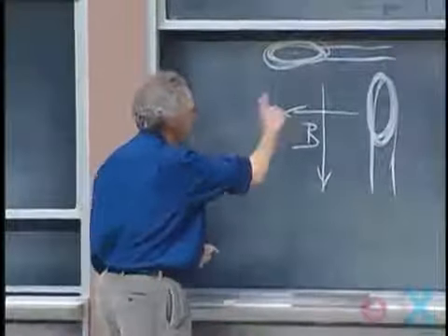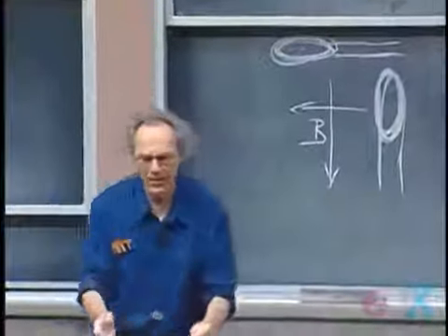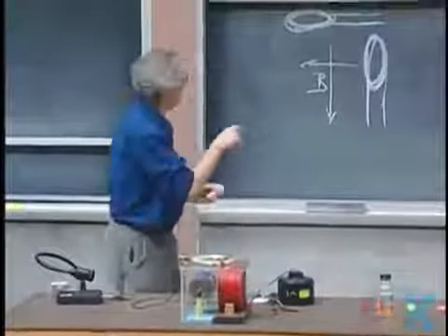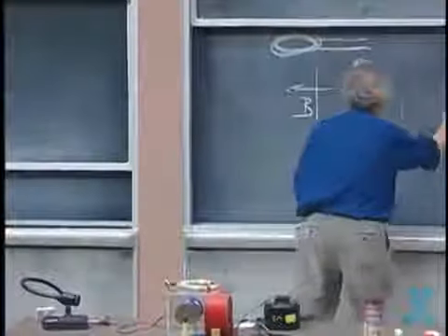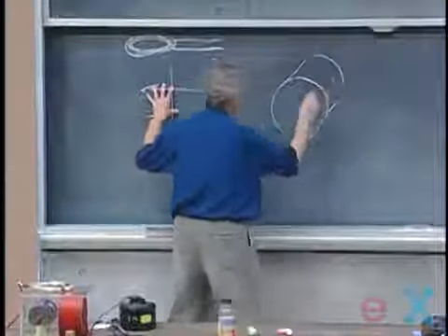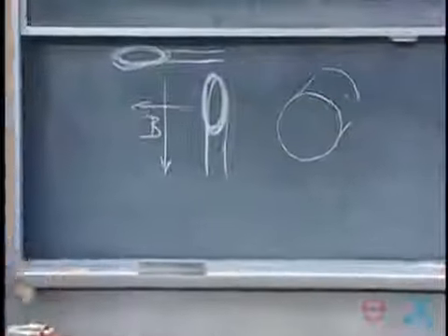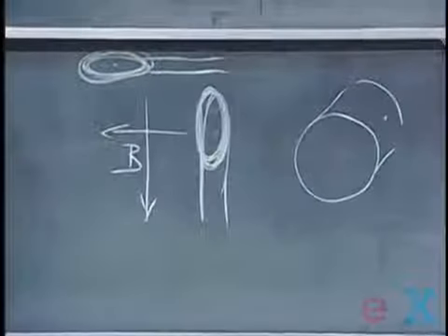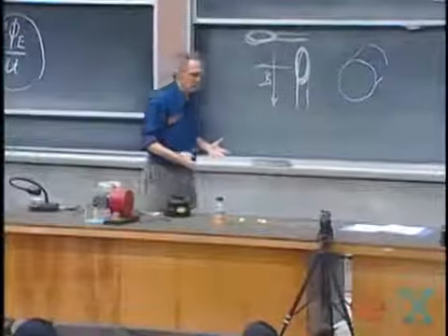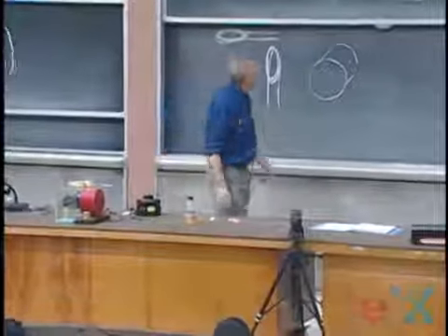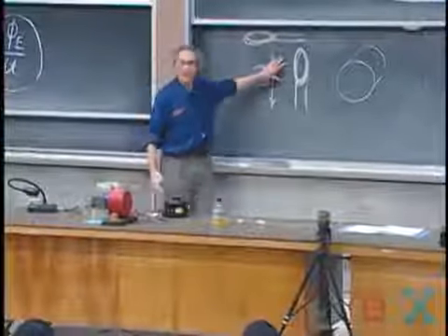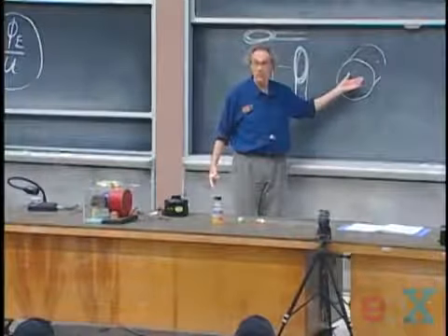And if I put in here a can, a paint can, we use a coffee can, it's right here. Then at the surface of that can, so I will draw the can here, but it's really there. At the surface of that can, you're going to have eddy currents, because you have change of magnetic flux all the time, and these eddy currents with the magnetic field will cause a torque on this can.